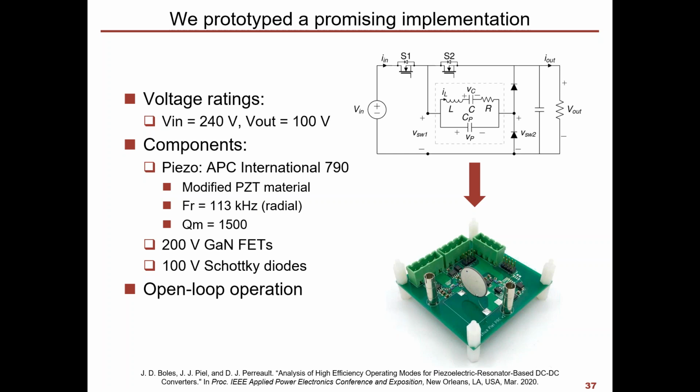I don't think so, because like any traditional converter, each of these switches is on only for a certain span of time per cycle. It turns on at the switching frequency, once per cycle, and turns off that many times as well. It's not turning on and off multiple times per cycle. So I think it should be about the same as other converters.